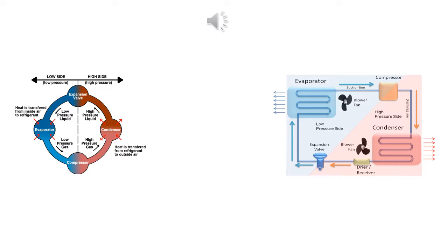To understand how the refrigeration cycle works, you must understand the relationship between volume, pressure, and temperature. All AC and refrigeration systems depend on the pressure differences present in the system. The reason pressure is important is because of the fluid used in the system. The boiling point and condensing point of refrigerants can be lowered or raised with a change in pressure. So if the volume, the area that the refrigerant has to fill, is held constant, and we lower the pressure by restricting the flow of refrigerant, the temperature at which evaporation happens will be lowered.